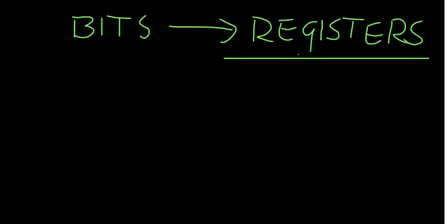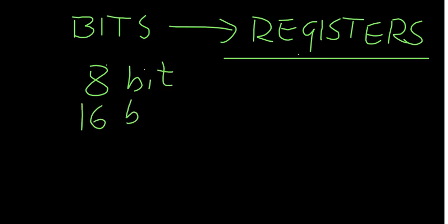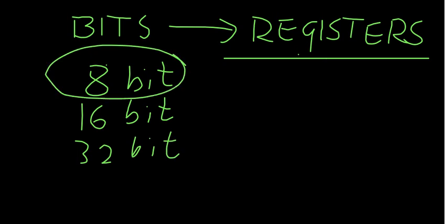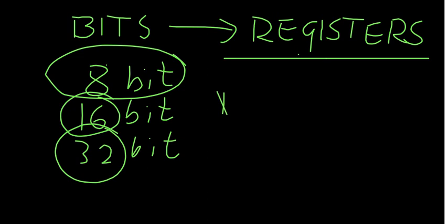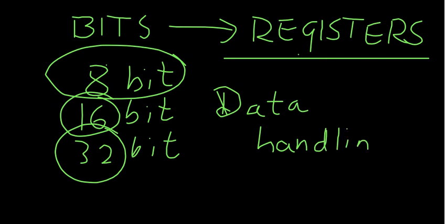How do you place them in a bitwise manner? Will it remain 8-bit data? Will it remain 16-bit data, or 32-bit data, or 64-bit data? And whether the type of PLC that you are using is able to accommodate that data if it is 32-bit or 16-bit. All those aspects are to be seen, and accordingly you have different data handling instructions in your PLC.